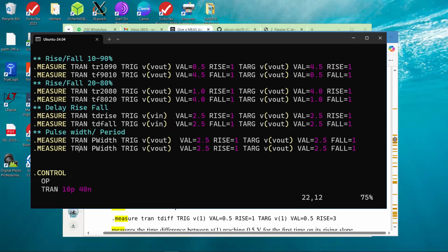No, no, no. It should come the pulse width which you have given, right? The other one should be from the fall, not from the rise. But how can it be zero? The first one you get is the 50% of the rise. Second one is the 50% of the fall. And that should be exactly equal to 20 nanoseconds, right? No, yeah, the ln of this thing, but the second one is the ln of fall, which is after 20 nanosecond, right? It's not at the same 20 nanosecond. Yes.